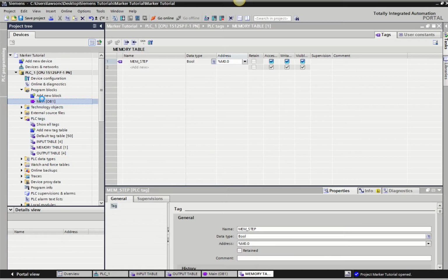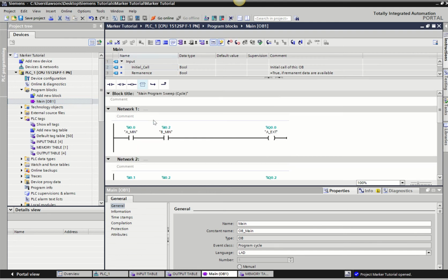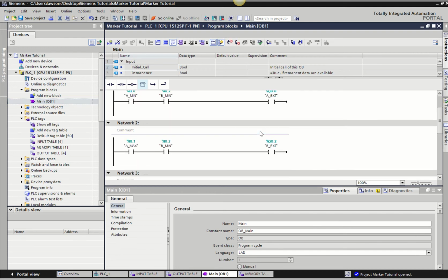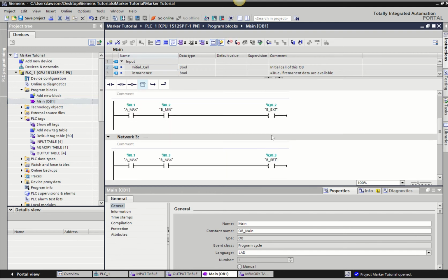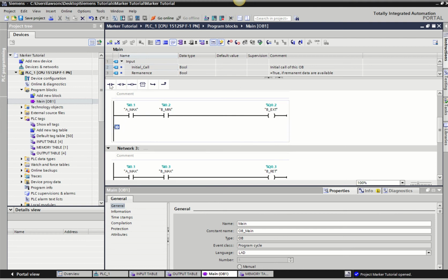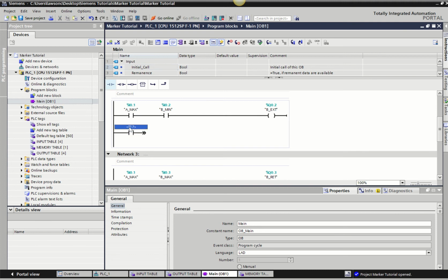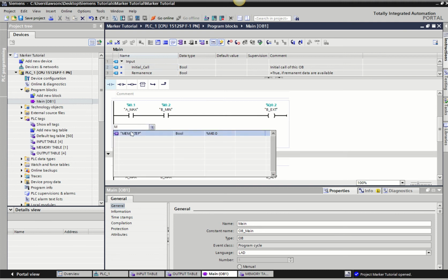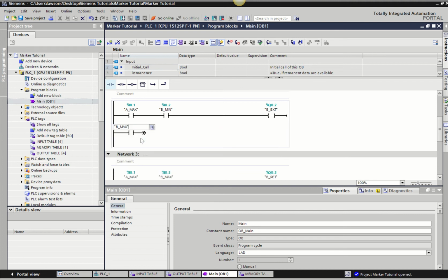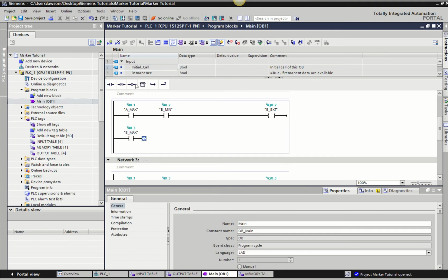So if we were going to code that up, we've step 1, we've step 2, then what I want to happen is, if I can just add in a new network below here, I just come in below here and add in a new line. And I want to memorize that ultimately B has gone out and extended and turned on a memory bit.